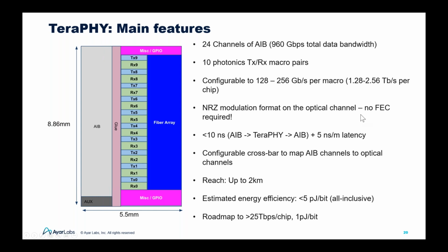Quick question. Obviously, we're really in transceiver land, as opposed to parallel bus land, and normally QSFP optical modules are converting transceivers from electrical to optical. What made you choose the bunch of wires approach, specifically AIB here, rather than just an extremely short reach channel? So you'd have, I guess, 100 gig or something like that, transceivers on the silicon, taking up far less area, being able to use organic substrates. Why choose AIB and not an extremely short reach channel?